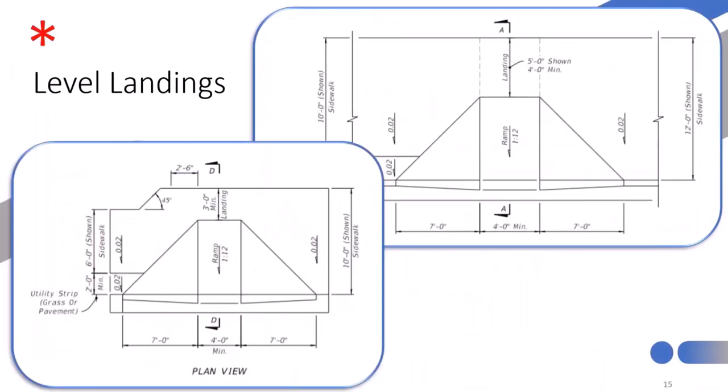Now, on your screen are two examples of curb ramp details from the standard plans. I wanted to point out that the lower left shows an upper landing, if you will, at the top of the slope surface of 3 foot minimum. This detail should only be applied where the site footprint is restricted and a wider landing is not achievable.